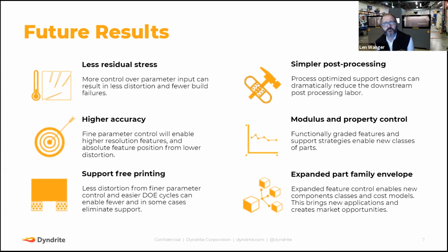So we actually want to be able to measure that residual stress in areas where we're not printing, and at times put things that are similar to a support structure or a mask to try to use the thermoplastic as glue to hold those layers together to prevent the part, particularly if you have a thin wall, from ripping itself apart. So that's a very different type of geometric query I'd like to be able to do potentially, is what the residual stress is in areas where we don't print.